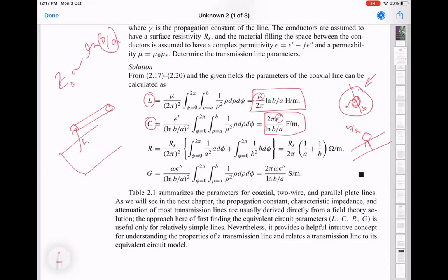But there are infinite choices, right? Just like we know that there are infinite choices for L and C to get the same L over C. But what will change is the velocity of propagation of signals on that coaxial line. If you go to the limit with large L and large C, then the velocity will be slow. If you go to the limit with small L and small C, then it will be faster. And as L and C become smaller and smaller, ultimately you hit the limit of free space propagation. In fact, I think for coax with an air dielectric, the velocity is that of free space. I have to double check, but I think that's right.